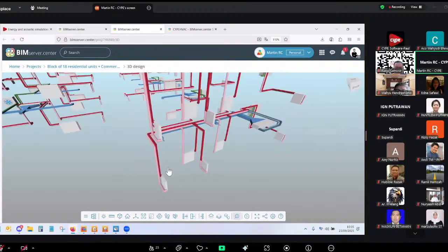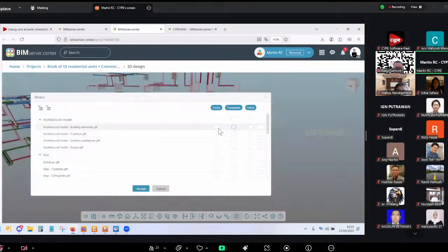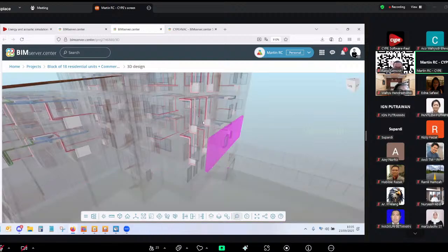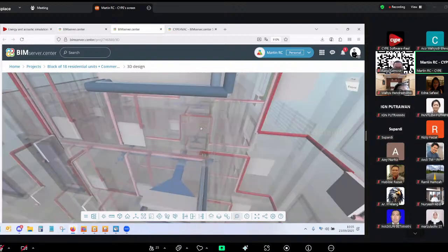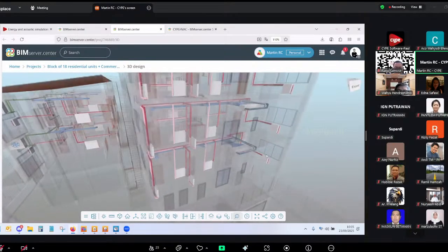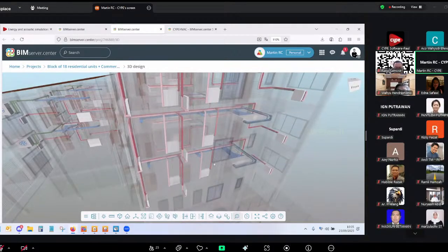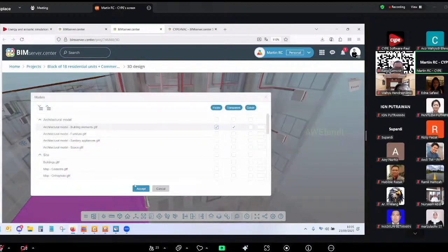So in this case, this is the HVAC project of that same building. So advantages. First of all, we don't need to model the same building again and again. We don't need to be drawing the same CAD 8 times. Then if we calculated the thermal load, I am able to use that information and automatically size the equipment of the HVAC, and also being fast in the development of that project.